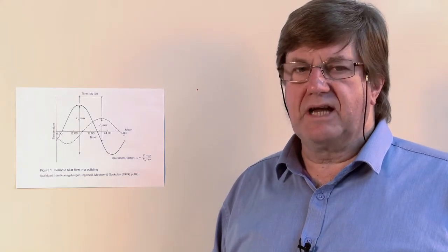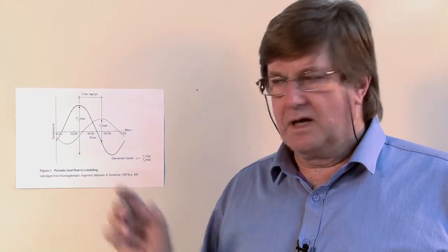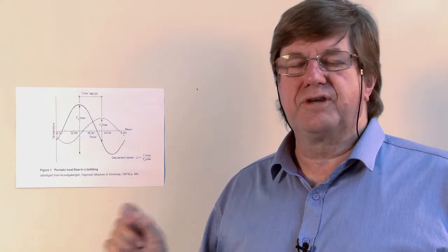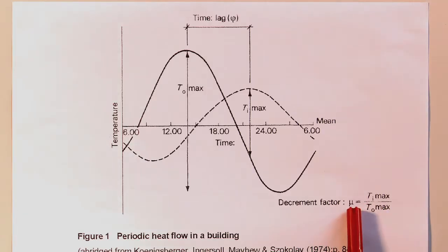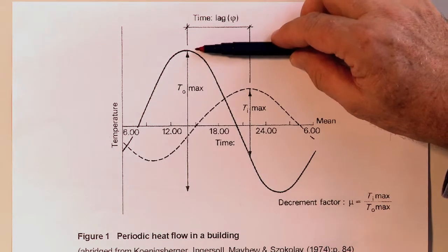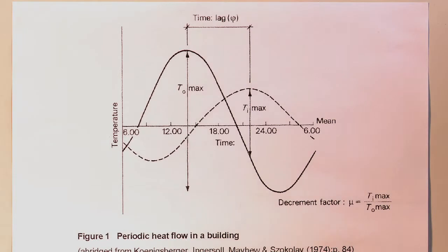Usually in brick veneer construction, we introduce some insulation. The insulation also increases the temperature drop. And so every wall configuration has a different decrement factor. It's never 1, because if the decrement factor was 1, then the outside air temperature would eventually be achieved internally.